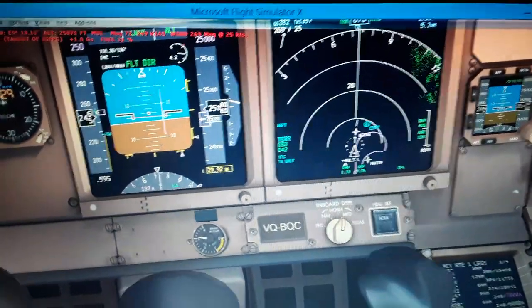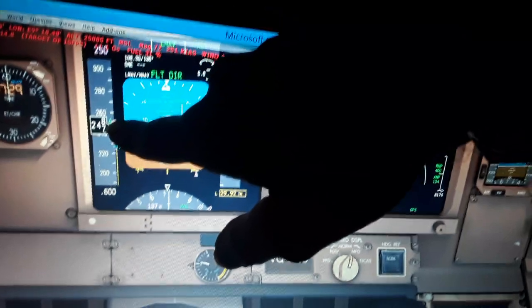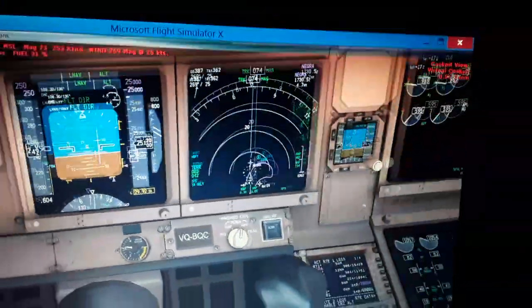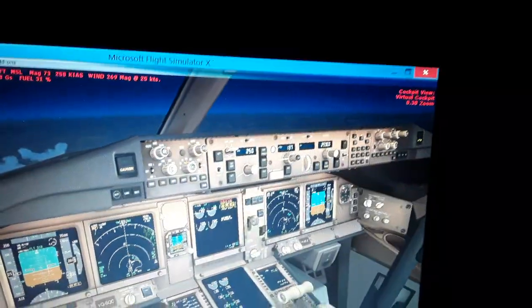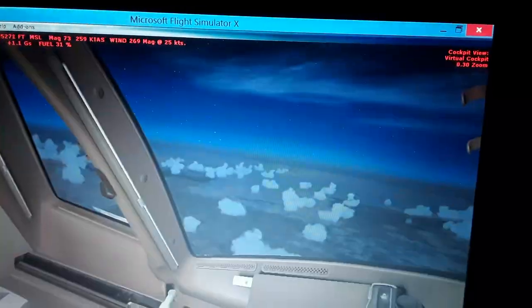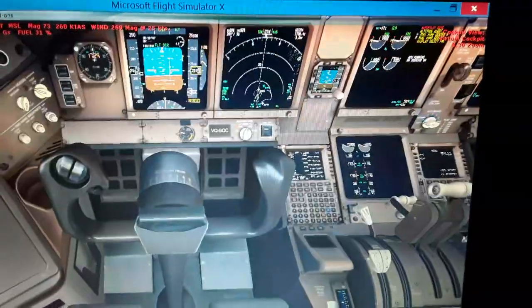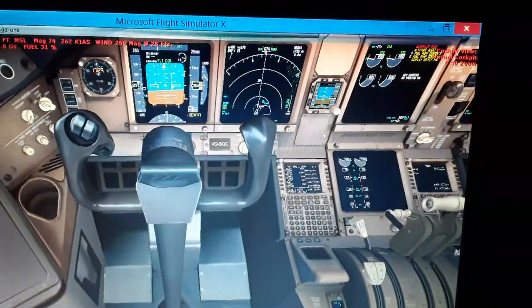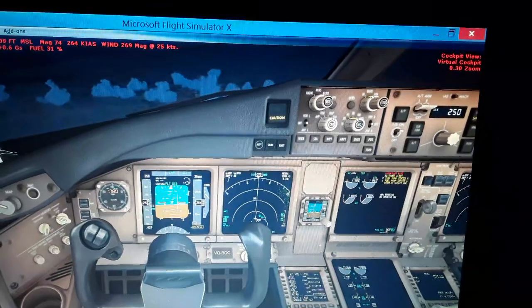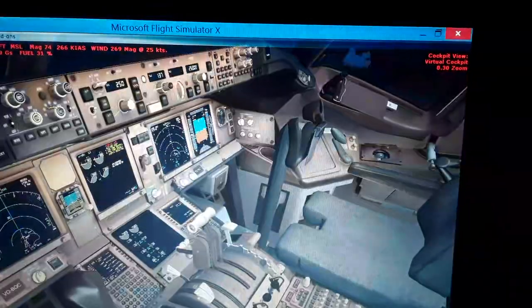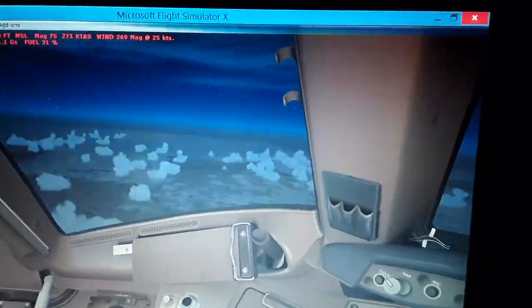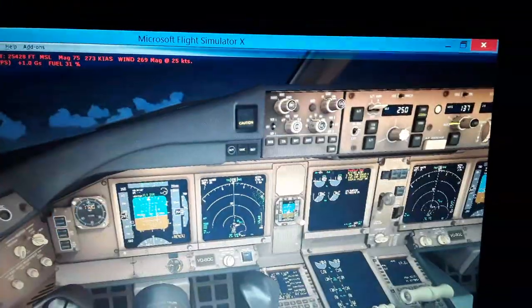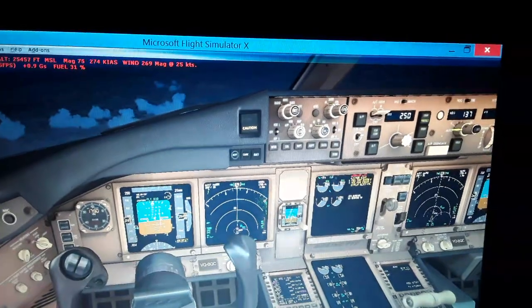We don't need so much thrust. You can see the thrust strength here. The airspeed is increasing. So now we fly completely manually, both thrust and pitch and roll, using the bank roll from the control column and wheel here. We need to adjust pitch down a little bit, not pitch over our position. Leveling off, it's not easy.